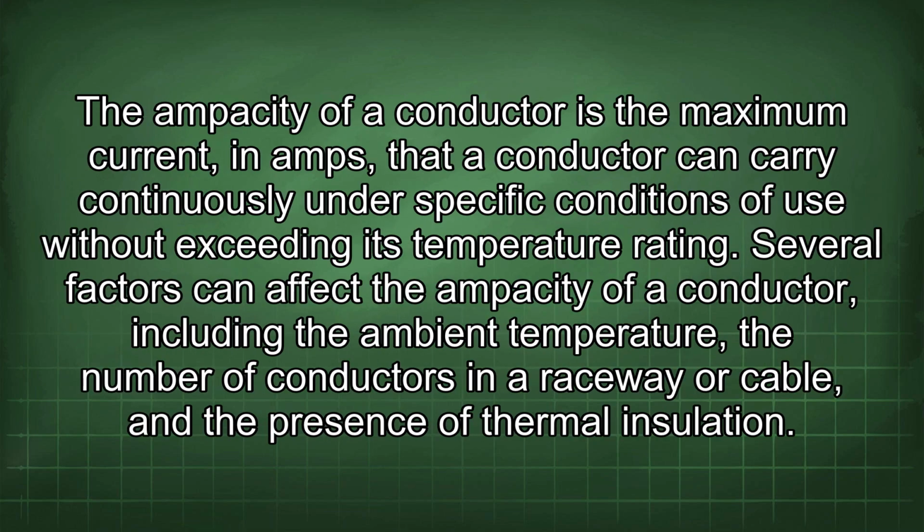The ampacity of a conductor is the maximum current, in amps, that a conductor can carry continuously under specific conditions of use without exceeding its temperature rating. Several factors can affect the ampacity of a conductor, including the ambient temperature, the number of conductors in a raceway or cable, and the presence of thermal insulation.